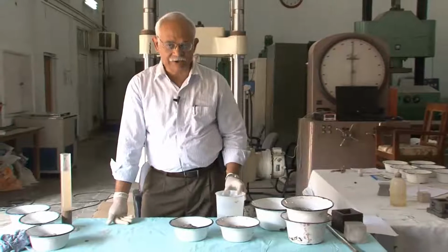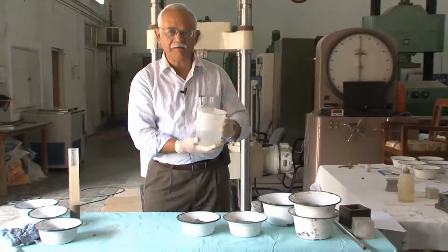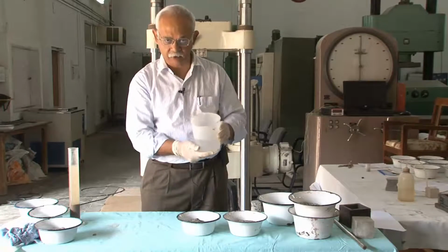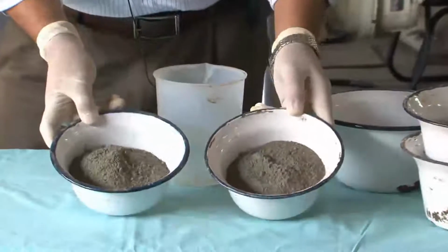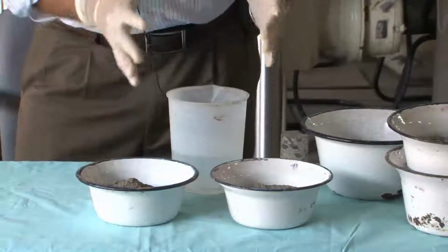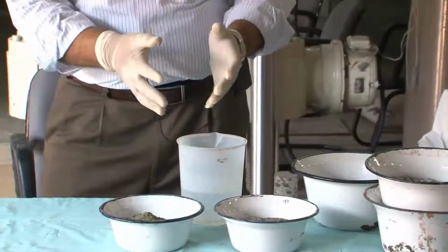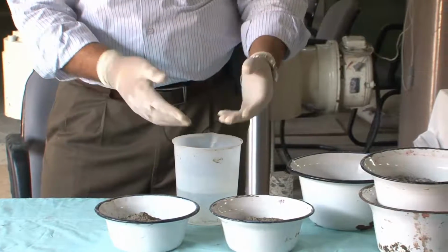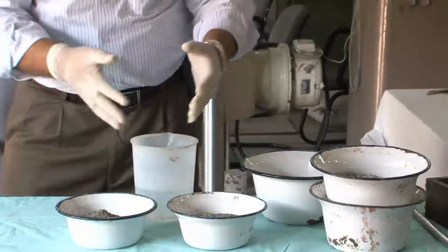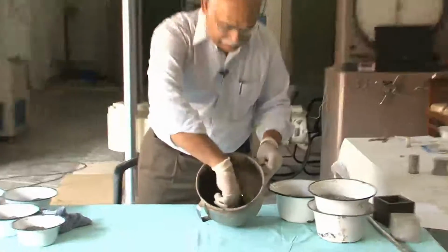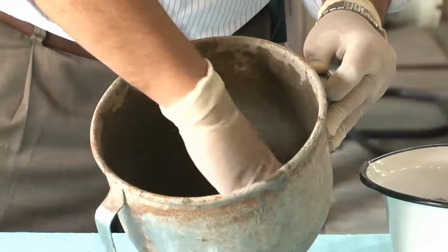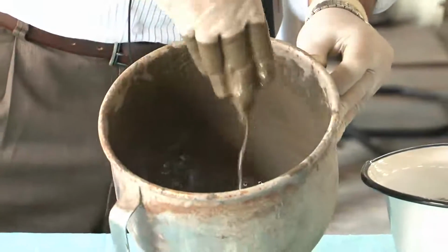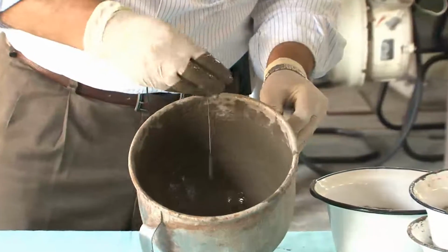To make the discussion quantitative, let us take half a kg of water, which is 500 ml of water, and we will mix this with a kg of cement. Now, what that means is that the water cement ratio of that paste will be 50%. There is 500 grams of water and 1000 grams of cement. Mixed, we will get a water cement ratio 50% paste. This here is the cement paste that we have, having a water cement ratio of 50%. I would like to draw your attention to seeing how fluid is the paste.